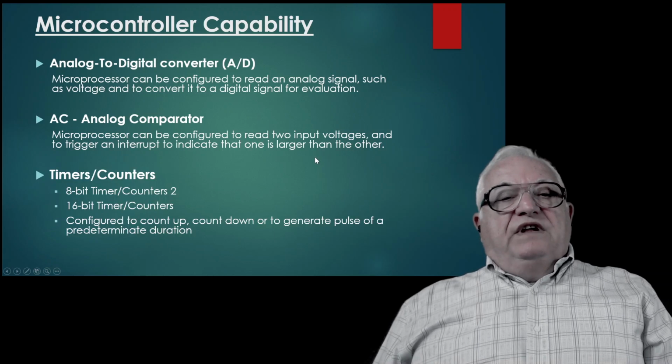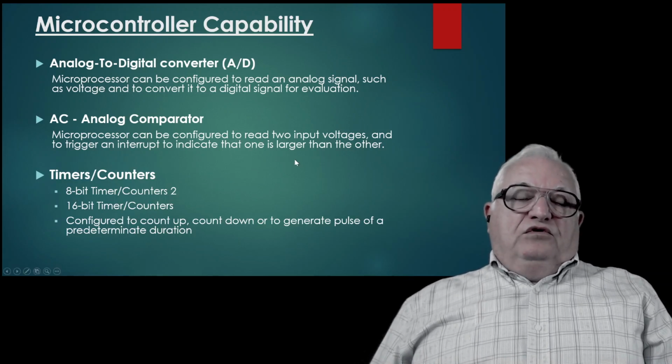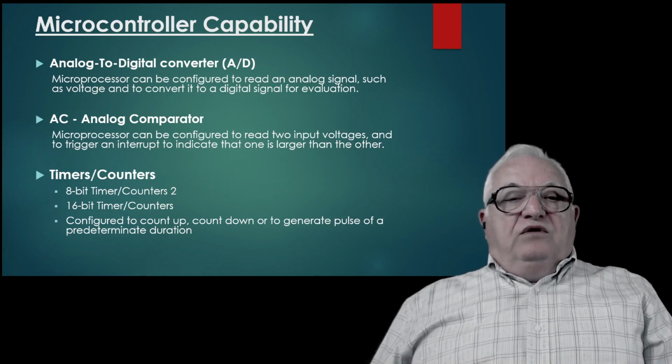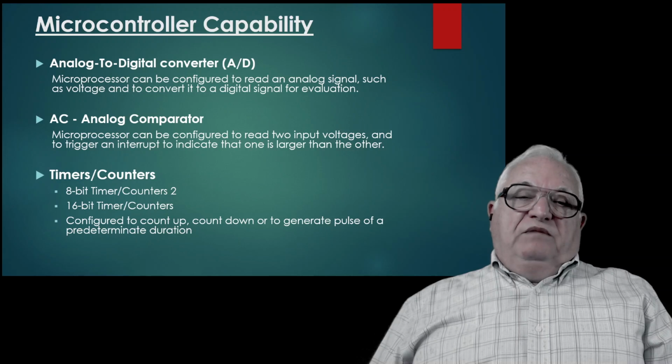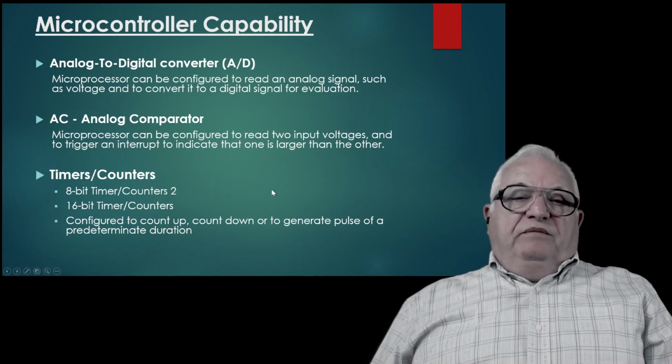Now we have timers and counters. The microcontroller provides two 8-bit timer counters and one 16-bit timer counter. Those timers can be configured to count up, count down, or generate a pulse of a predetermined duration.